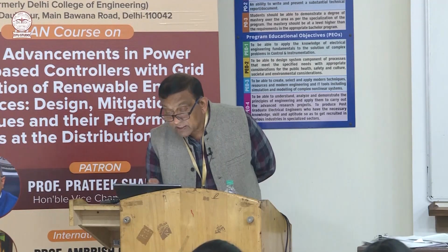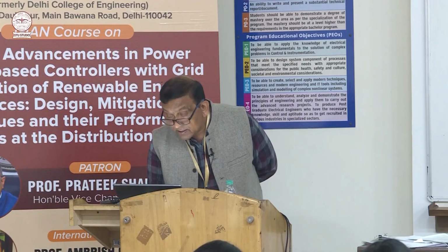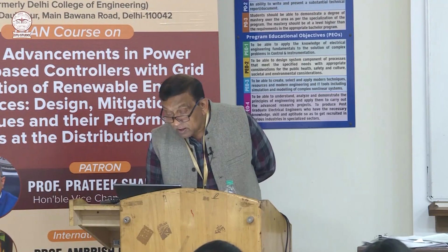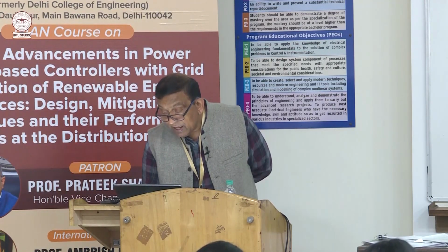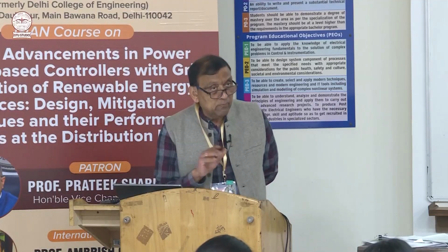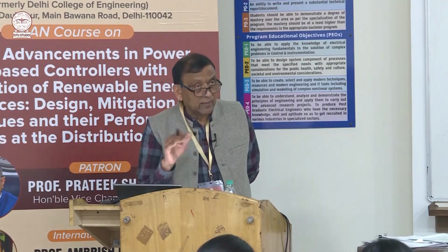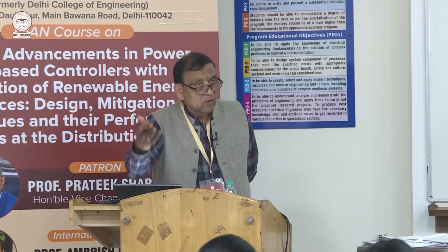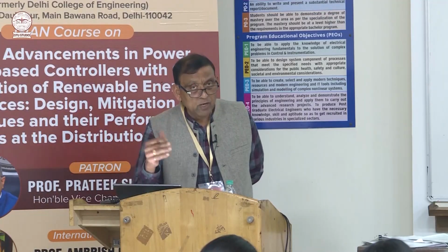So if you take the sum of these, this will cancel out, this will cancel out, and the 11th harmonic is added. Similarly, the 13th harmonic as well. So it means that it is not helping with the 11th and 13th harmonics, but again on the 17th and 19th harmonics it is cancelling.